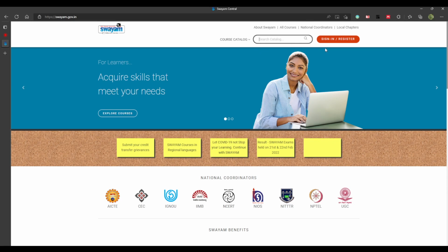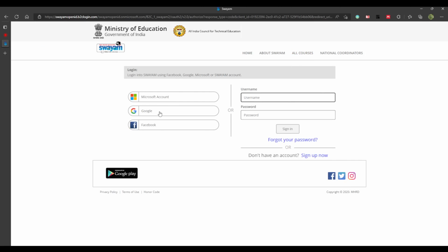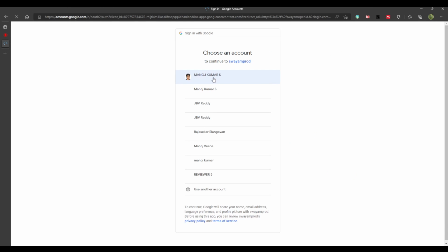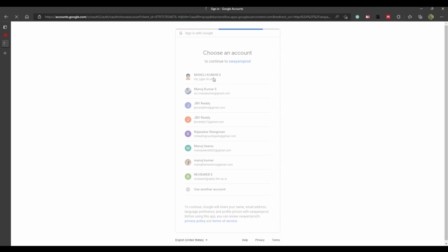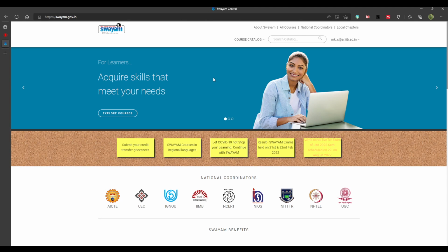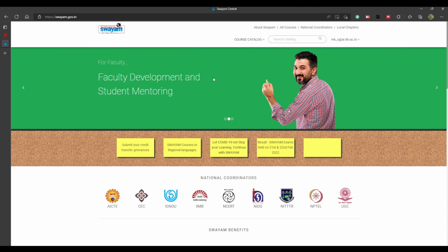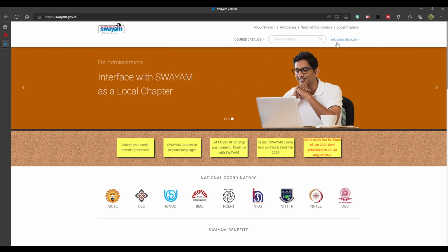Here the data given to you is resistance per inch. You multiply them with their respective thicknesses and add each one's resistance value to get the total resistance. Then you take the reciprocal and you will get the U value. Did you get it? Could you solve it and show it, please?